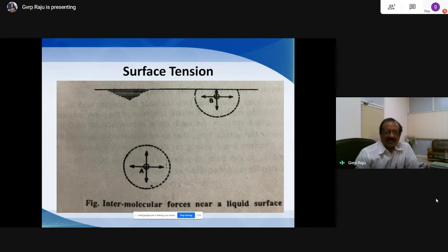It is not coming down, and it is also in equilibrium. It is also in a rest condition. The reason is surface tension. Whatever the net downward force on the fluid at the surface, it will be counteracted by surface tension. If you see here, this is the upward force. The upward force is due to the surface tension, which counteracts the net downward force.